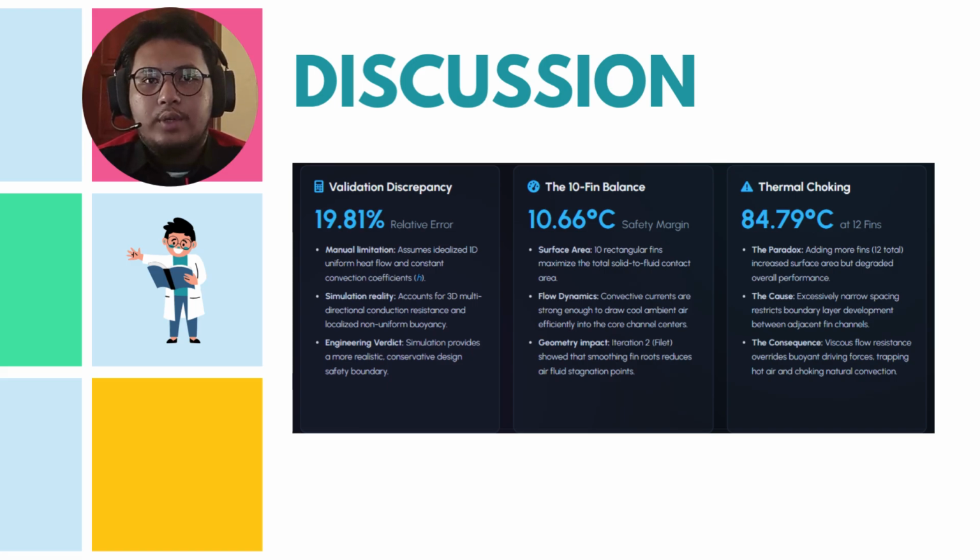As for our 10 fin design, it gives us a comfortable 10.66 Celsius safety margin. It provides the perfect balance: enough surface area to let the heat escape, but enough space between the fins for cool ambient air to flow smoothly through the channels.